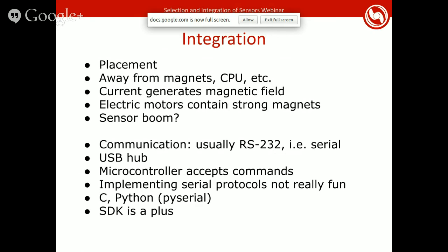And that's a thing we have that's elevated from outside of the hull and is away from any kind of wires with large current or magnets or interference. So if you have a lot of stuff going on in the hull, it may be a good idea to consider dedicating an enclosure particularly for this purpose, namely a sensor boom. You want to keep that away not only from the wires, but also from the thrusters.